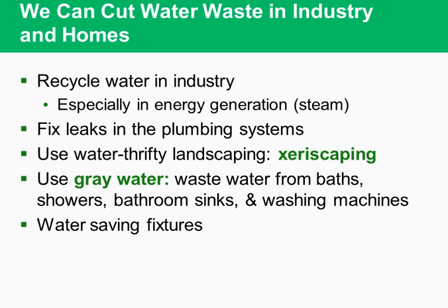Or use gray water. Gray water is wastewater from baths, showers, bathroom sinks, and washing machines. Basically, it's everything but your toilets. Some people, you don't want to use that. But if you can redo your pipes so that this gray water can go outside, you can use it. You can create a rain barrel for it, or you can just have straight up piping for it, and it will just immediately dump onto a particular bed that you need watered.